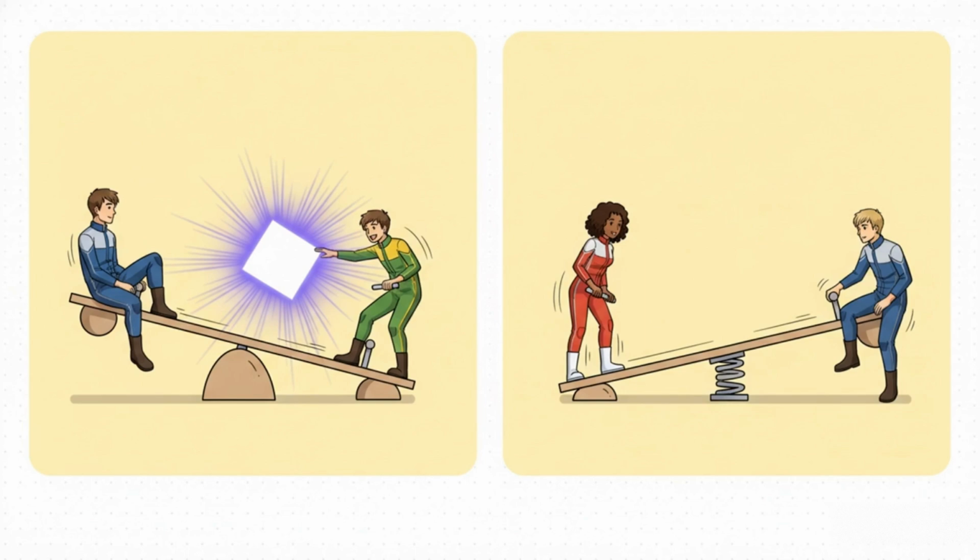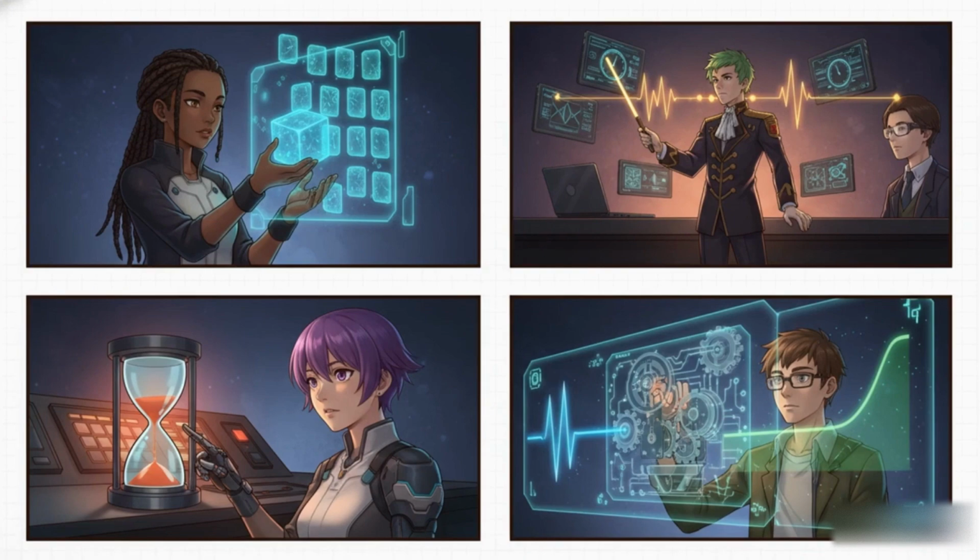And finally, there's the monostable. It has one state it loves. You can trigger it, push it over, but it'll always pop right back after a specific amount of time. So what do we get from these different personalities? The bistable, with its 2 states, becomes a memory element, a flip-flop. The restless astable circuit becomes our digital clock, providing that steady beat for every computer out there. And the one-shot monostable becomes a super precise timer. Oh, and here's a cool little trick. If you take that sharp square wave from an astable and integrate it, you can smooth out the edges and create a perfect triangular wave.